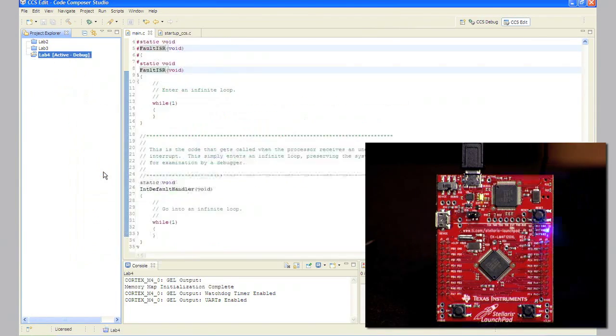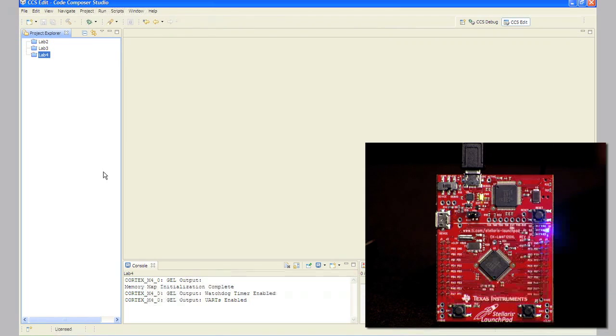Investigate the pulse width modulation capabilities of the General-Purpose Timer. Program the timer to blink the LED faster than your eye can see it. That's usually above 30 Hertz. And then use the pulse width to vary the apparent intensity. Write a loop to make the intensity vary periodically.